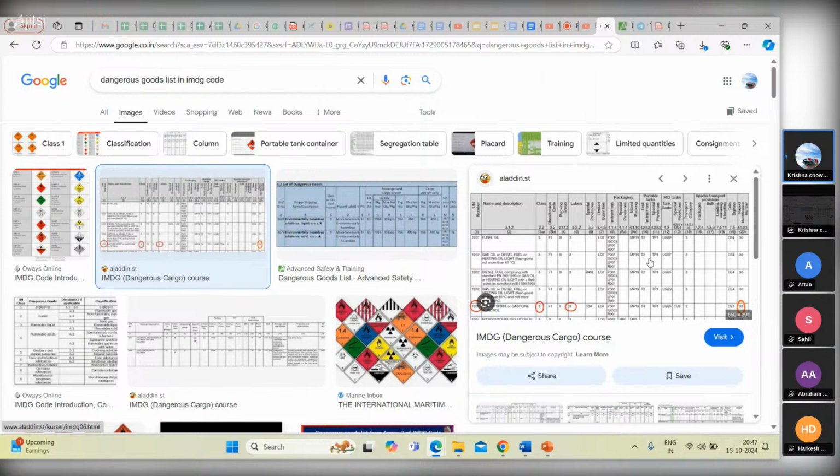Maybe he transported the same cargo 6 months or 2 years back, but depending on the storage space it might have different properties. So it's the latest sample analysis, including properties, dangers, moisture content, and precautions required during your voyage. But MSDS is general, with all the properties and dangers of the cargo substance as such.